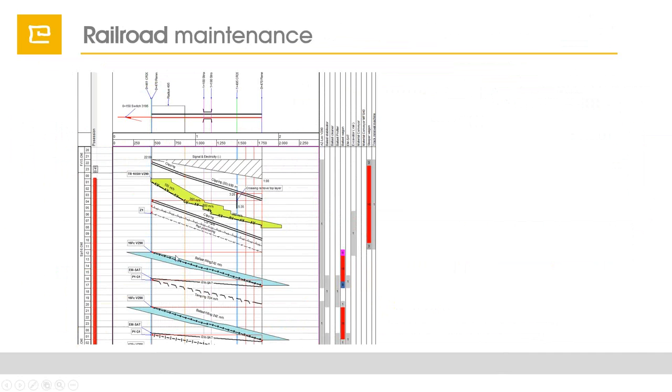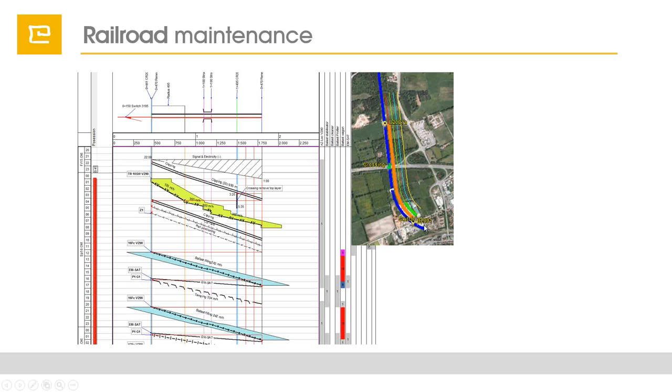This is followed then by the activities where the ballast is put to the rails. Then we have the tamping and another ballast section, and this is followed until the end. The rails are again welded. We also made an animation for this so that you could see the project in the Google Earth map, where each line is representing one activity here in TILOS, and then you can see how they are moving.